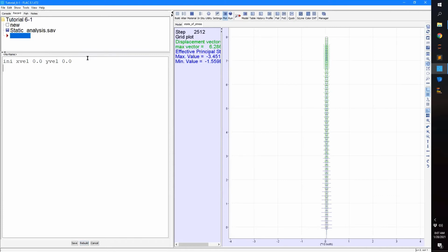So now another important question would be, do we want to zero the displacements? In many cases, what I've found for seismic analyses is that for the pre-earthquake analysis, what we're primarily interested in is the stresses and not the displacements. Usually the models that we have are simpler, given the focus that we have on seismic analysis.